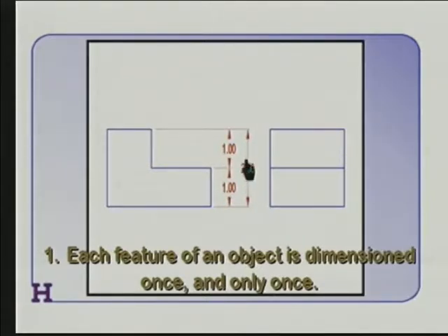That means that the overall height of this object, according to the large dimension here, is plus or minus 10 thousandths. However, if you add this one, the step here, and suppose it was as big as you could allow, plus 10 thousandths, but suppose this part was as big as you could allow, plus 10 thousandths, now you have a problem, because if you add these two up, you can have this 20 thousandths larger than the average.